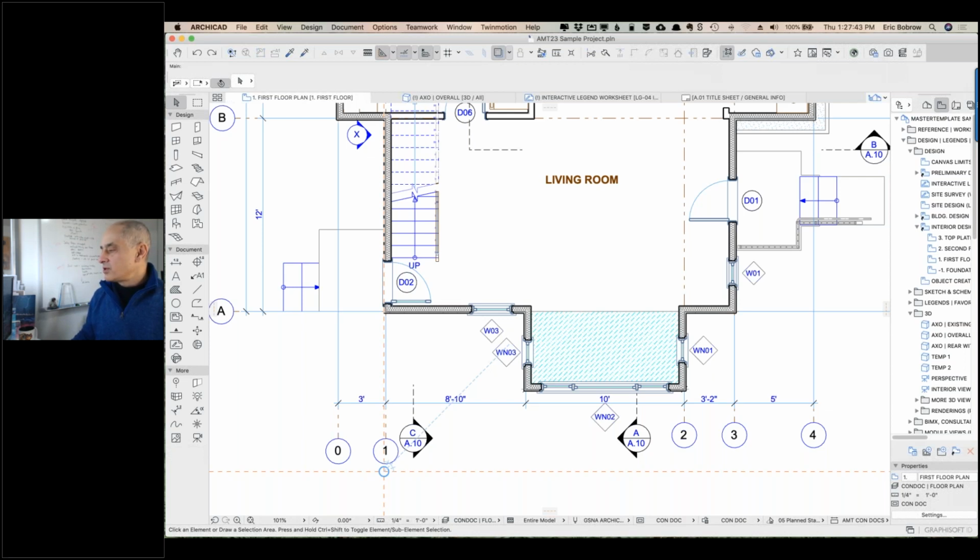Hotspots come in handy for dimensions. Okay, so you can put hotspots. Some people are unaware that there is this little hotspot tool. So, little beginner tip. The hotspot tool is something that you can activate from the More palette. Sometimes this is closed up. Sometimes you need to open it up. The hotspot tool allows you to place non-printing node points or snap points. You can see how this snap point, my cursor changes when I hover over it.